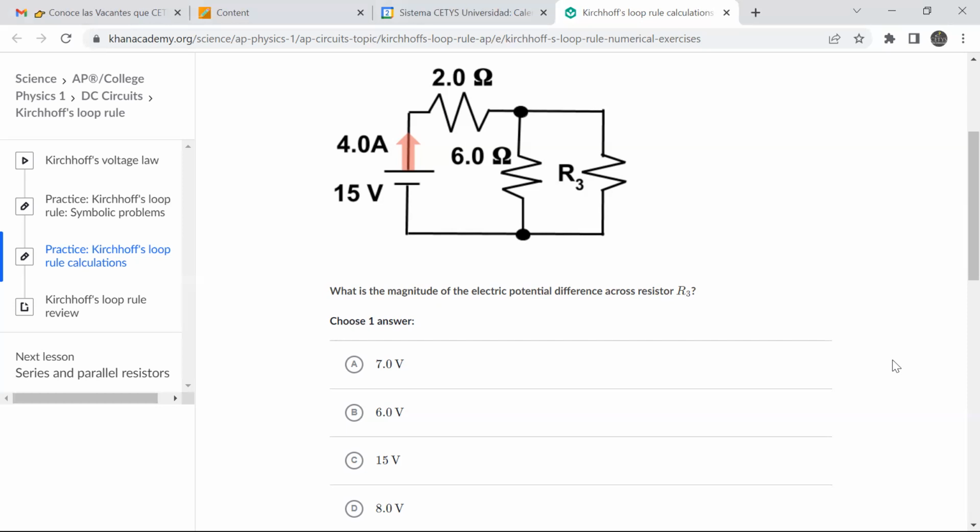There are many ways, by the way, we could solve this one, but I want us again to practice Kirchhoff's law. So a question again, just to practice: how many loops do we have in that circuit? Remember the definition. So this is loop 1. This is loop 2, and remember that we've got a third one.